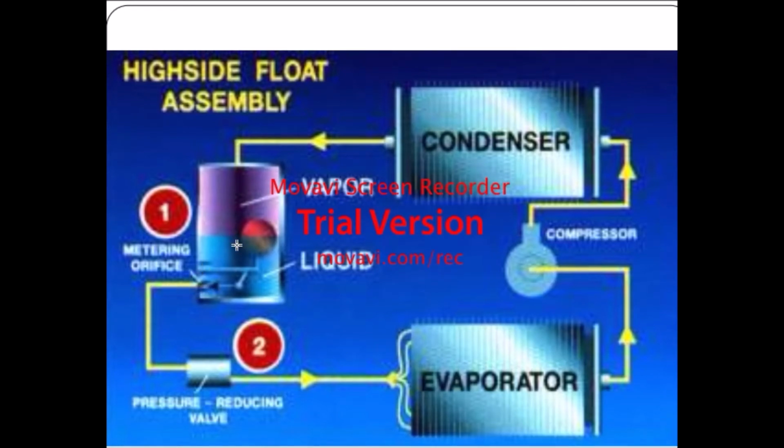If the float is lower, we will close the valve. So we need a high surface level of the refrigerant to open the supplying of refrigerant into the evaporator. That's why we call it the high side float.